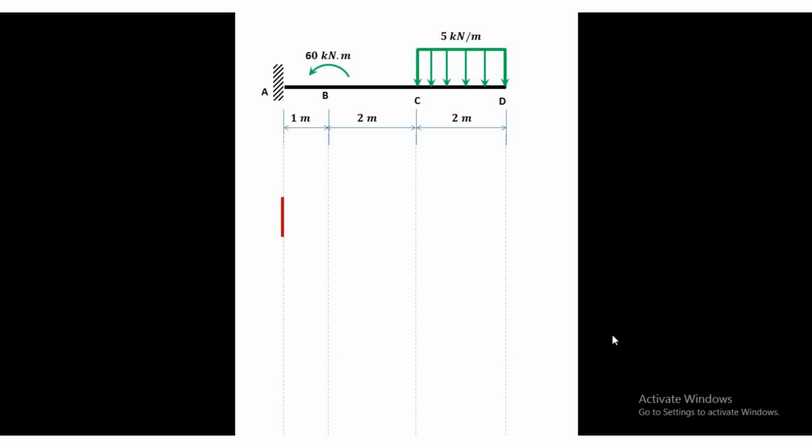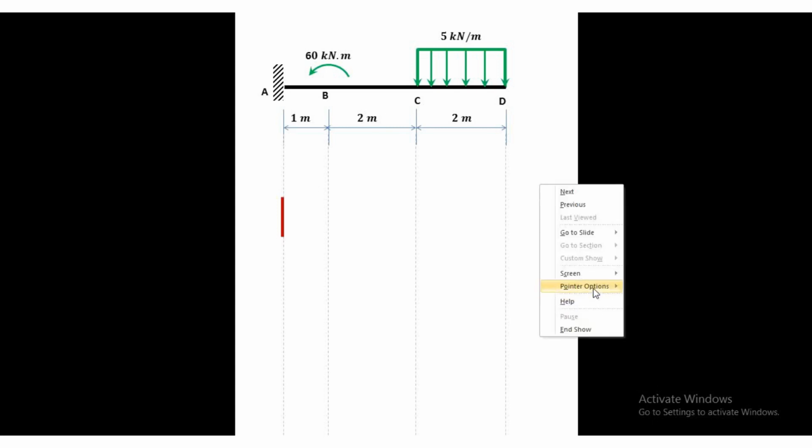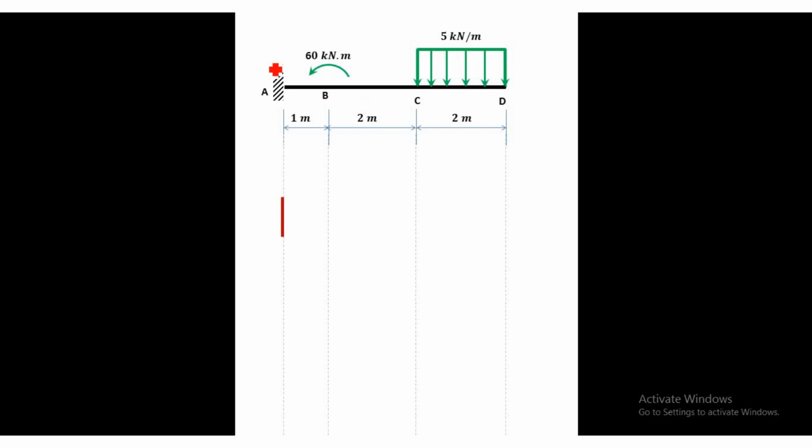Wala itong problem na to sa notes nyo. I would just like to show to you yung diretsyon na para hindi na kayo nagsusolve or nagsusulat ng madami-daming equations. Again, for this problem, you are required to draw the shear and moment diagram for this cantilever beam. Now, the very first thing you have to do is to determine the reactions for this cantilever. Now, since dito ay fix, meron akong RA. Magzi-zero out yung horizontal reaction dito kasi wala namang horizontal force.